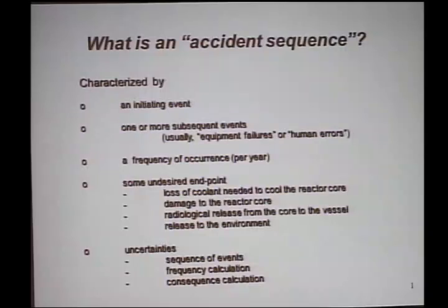But even though they're 3, 4, or 5, they can happen, and the key was 2 things: to identify the sequences. It's a pump, then it's a valve, then it's a human error, then something. And by the way, a lot of them are human errors. In other words, 2 things fail, and the human in the control room's got to do something. The probability that he gets it right isn't 100%, it's only 99%. 1 time in 100 doesn't get it right. And we have data about that, by the way. We have data on human errors, actually real data from things that are collected in the real plants that are running today, and we collect those data.